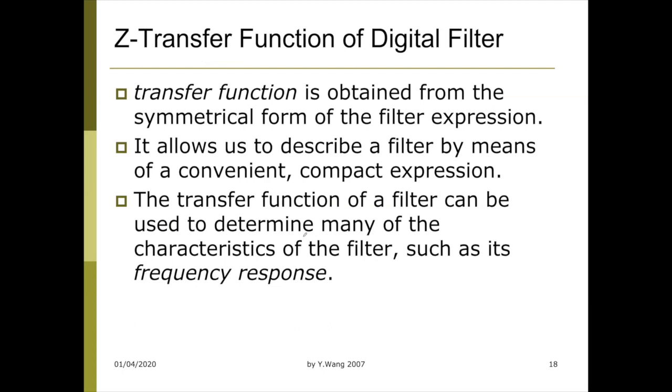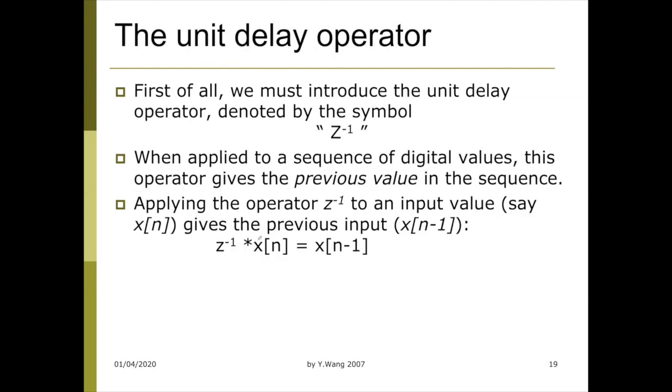With the transfer function, the filter can be analyzed in terms of its characteristics, such as the frequency response. How we convert a difference equation to Z transform form is not very difficult. By doing that, you'll be able to understand lots of textbooks and help files in MATLAB, because most of them express filters in the Z transform format. So, let's have a look at this process.